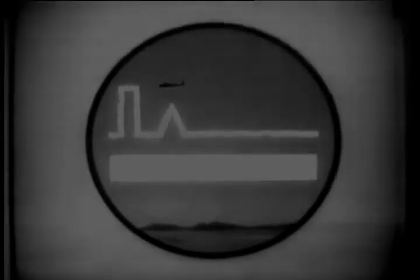So much for measuring azimuth and elevation. You'll remember that to measure range, you need only a single pip, A-scope, and the distance from the pip to the main bang represents the range of the target. As the target approaches your set, its pip approaches the main bang. The baseline, or sweep, as we've said before, represents the full range of your set. When we pick up a target somewhere within that range, it's obvious that the longer the baseline we have to represent the range, the easier it will be to read our target's position accurately, right down to the last yard.